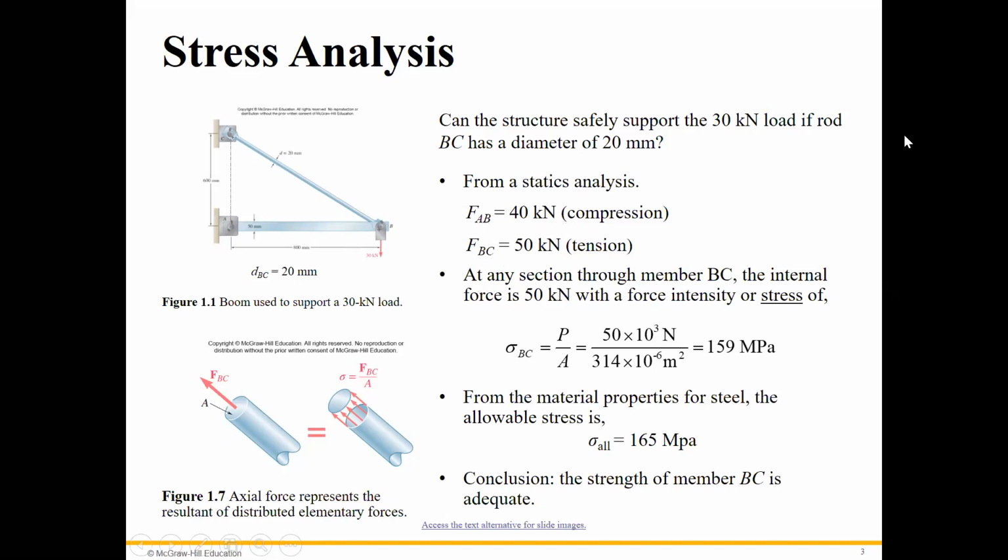So, we are asked, and also this is member BC, this rod. Member BC has a diameter of 20 millimeters. It asks us to first find the stress. So then it's very easy, right? Because the force in BC is 50 kilonewtons, right? And what is the area? Area would be just...